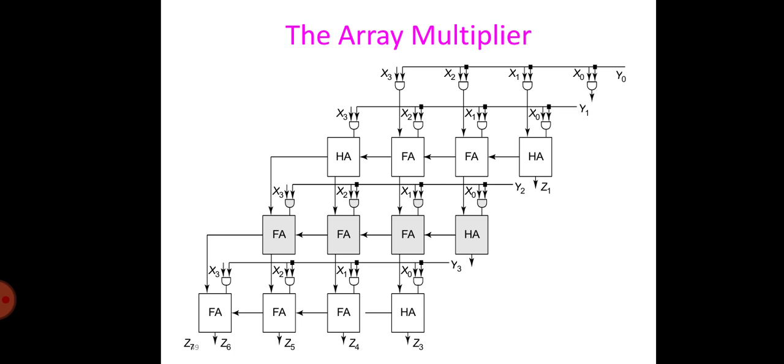Since all critical paths have the same length, speeding up just one of them, for instance by replacing one adder by a faster one such as a carry select adder, doesn't make much sense from the design standpoint. All critical paths have to be attacked at the same time, so it can be deduced that the minimization of T mult requires the minimization of both T carry and T sum, and in this case it could be beneficial for T carry to be equal to T sum. This contrasts with the requirements for adder cells, where a minimal T carry was of prime importance.